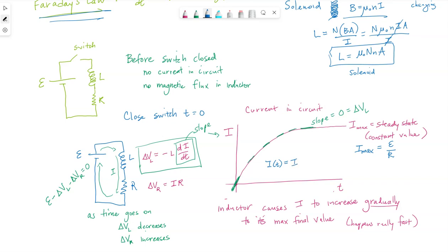Now, I don't like the subscript our author originally chose, and I'll explain why. So this is what our equation looks like, where tau is L over R, the value of the inductor divided by the value of the resistor. This is a time constant. It's how much time it takes for the current to increase to 63% of the maximum value.